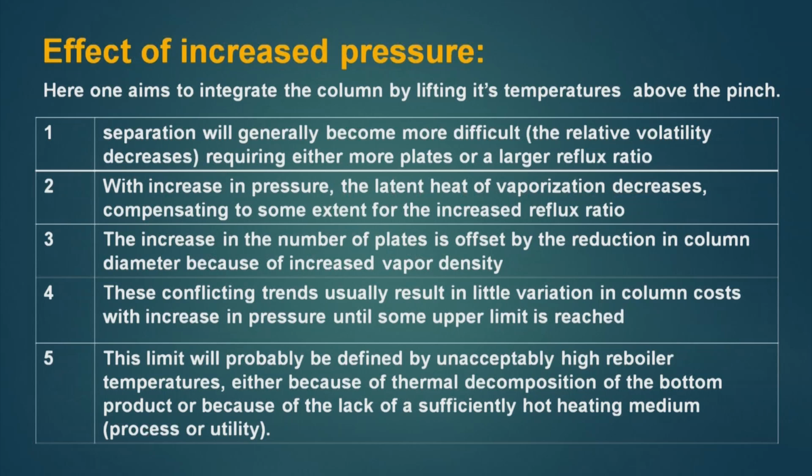Now, if it is so, then what will happen to the separation which is being done in the distillation column? Separation will generally become more difficult. Why? With higher pressure the relative volatility decreases, and if it is so, then it will require either more plates or a large reflux ratio to do the same separation.